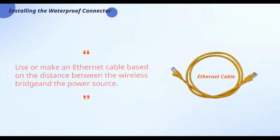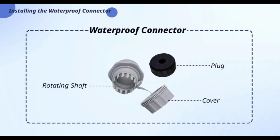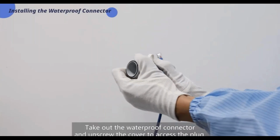Use or make an Ethernet cable based on the distance between the wireless bridge and the power source. The device supports PoE power supply, 5E or higher cables with a maximum length of 100 meters, 328 feet. As shown here, the waterproof connector consists of 3 parts: the cover, the plug, and the rotating shaft. Take out the waterproof connector and unscrew the cover to access the plug.